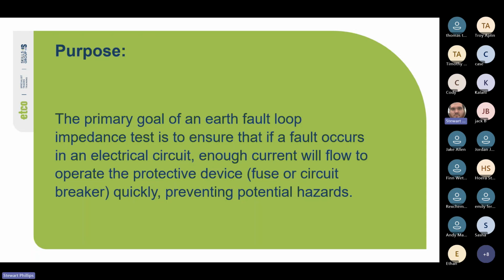Yeah, so in rural settings, because you'd be so far away, or it used to be an earth return path, sometimes that can be an issue. It's hard times. People are stealing copper off the transformers. They use about 3 or 4 earth stakes in one direction, and then at 180 degrees do 3 or 4 earth stakes the other way. And if the readings still aren't good enough, they'll put more in.